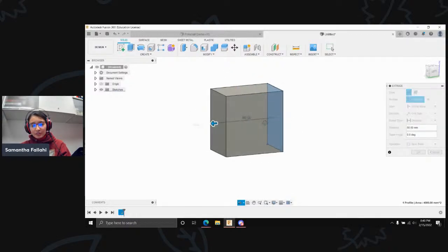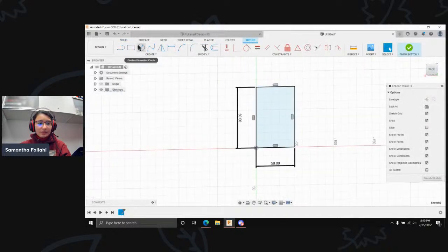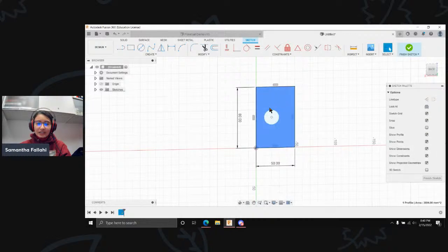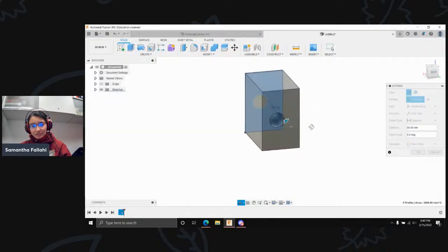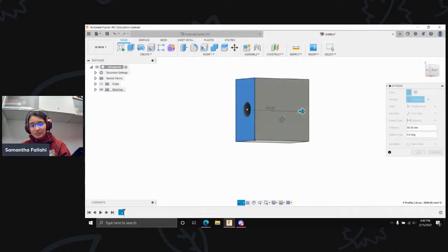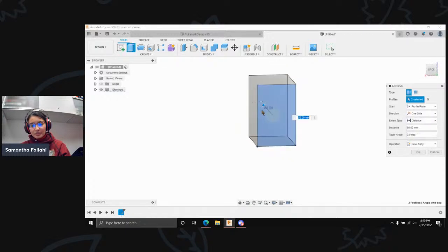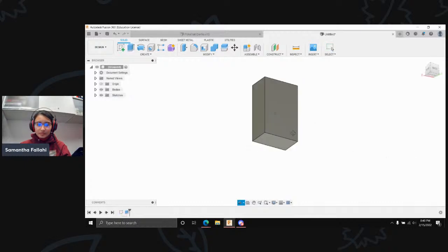So let's say I had a hole in the middle of my sketch. Let's create that right now. You'll see that it highlights everything outside of the circle. If I were to click E while having that highlighted, you'll see that it'll extrude everything except for the circle in the middle. If you, for some reason, wanted to extrude the circle as well, you would just click Shift, and it will become a whole rectangle. Easy peasy. So now we have ourselves a rectangular prism.